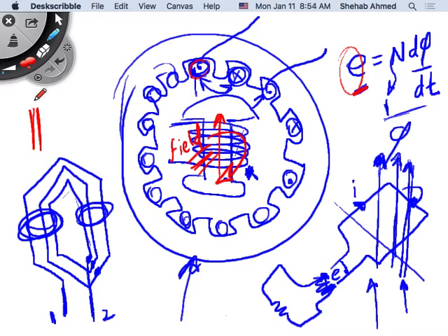because you don't know. Again, when you wind these things, the first turn will create a voltage. The next turn will create another voltage. Then the third turn, and you add all these voltages, and that's what you see here. So if the terminal voltage of each coil is 400 kilovolts, in the same slot I have a very low voltage, and I have a very high voltage as well. So you have coils or turns that have generated a very high voltage, and ones that have generated a very low voltage right next to each other, right? So you cannot do that. You'd have to insulate them significantly in that case.